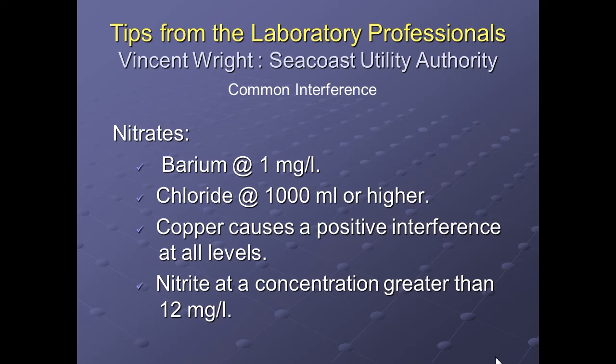Copper causes positive interference at all levels. If there's any copper in your sample and you're trying to test for nitrates, then it's going to give you a false reading on your nitrates.